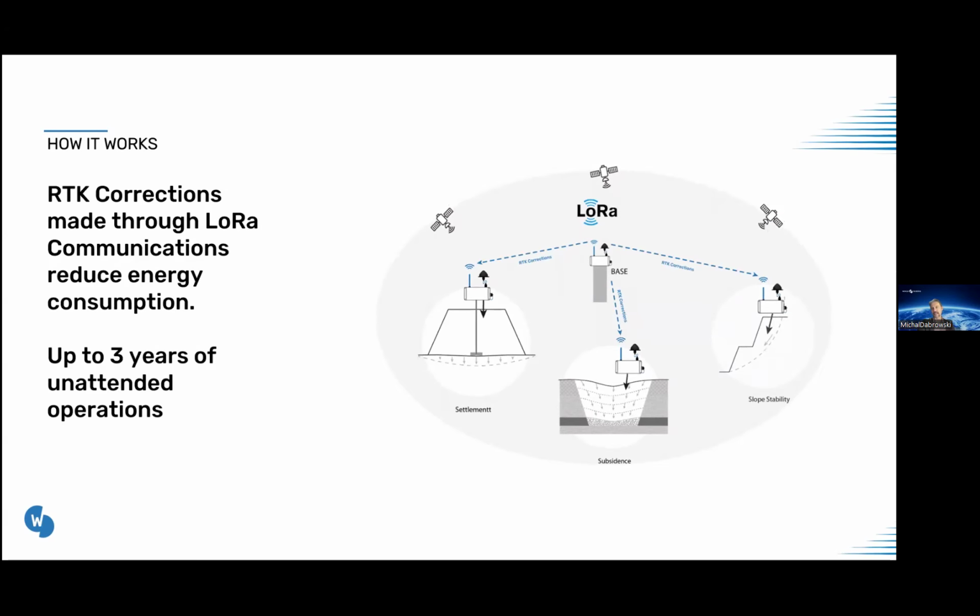I'm just going to mention we are using the LoRa communication protocol to distribute the RTK correction because this is very, very power efficient communication, or let's just say hardware. Currently, if you see a GNSS rover in the hands of a land surveyor, this equipment is most likely operating on either UHF radios or GSM cellular network communication, which requires a lot of power.